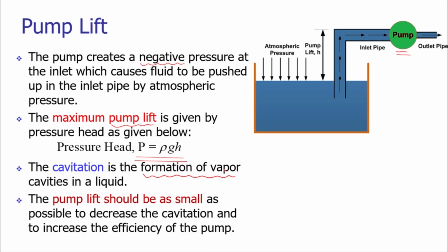That process is called the cavitation process. This cavitation creates problems, and it may also lead to failure of the system. So to have fewer problems inside the systems, it is recommended to have a lower pump lift, and that will lead to lower cavitation problems and an enhancement in the efficiency of the pump.